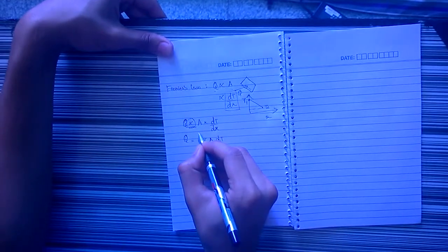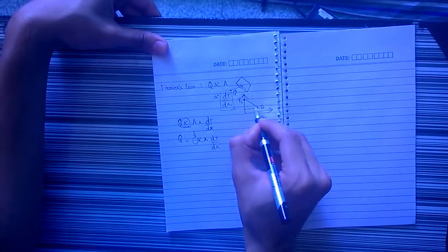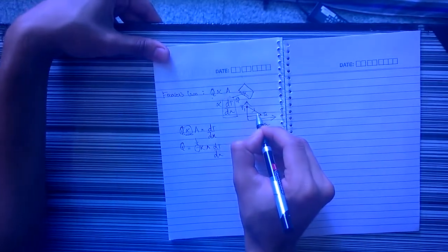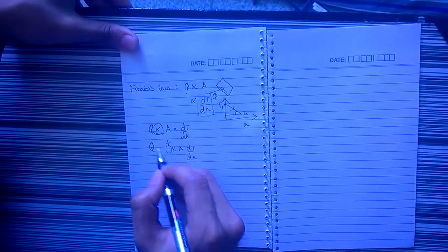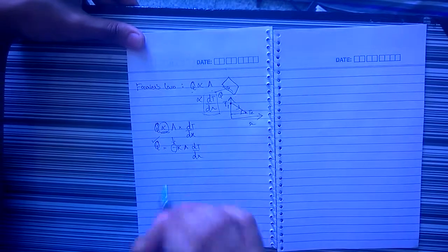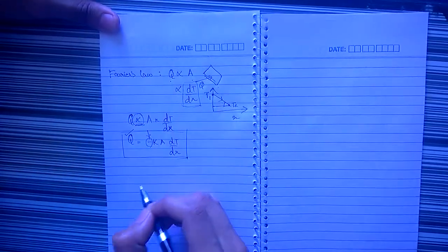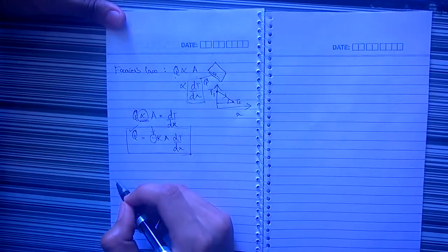Understand that we have taken this minus sign into consideration because there is a decrease in the temperature profile. Here T1 is higher than T2, so we find that the slope is actually negative, and so this negative sign is put here in order to make Q positive. So this is essentially Fourier's law of heat transfer. This is usually used for conduction processes.